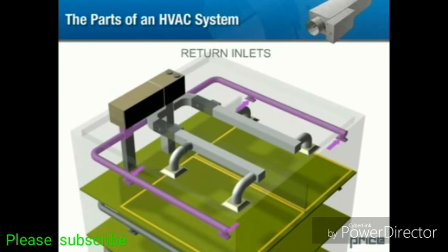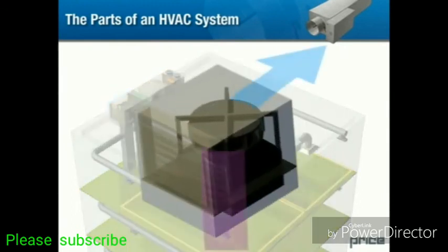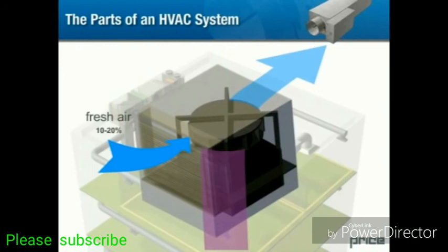Unlike an air outlet, a return requires no sophisticated vanes. However, the relative location of the air inlets and outlets can be critical to the efficiency of the system. Upon returning to the air handler, a certain portion of the return air is exhausted and replaced with fresh exterior air, in an average office building or commercial space, approximately 10 to 20%.